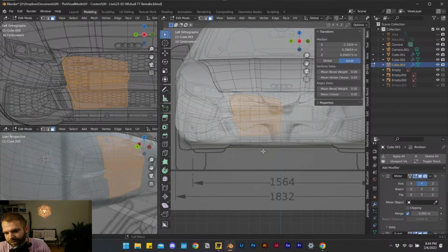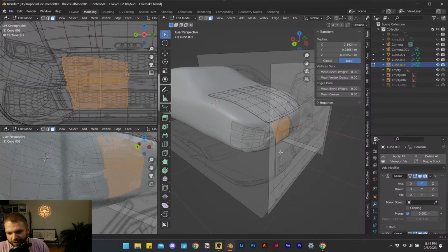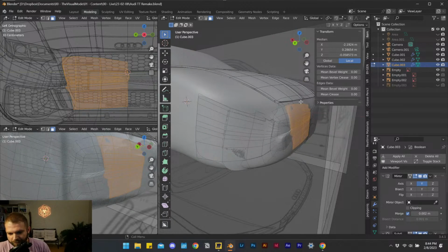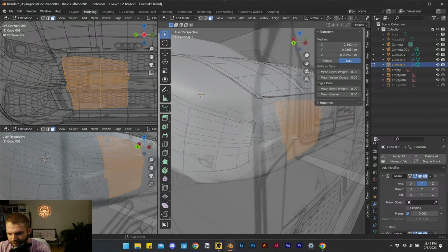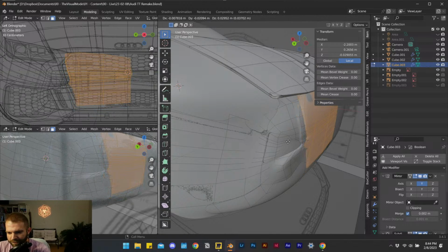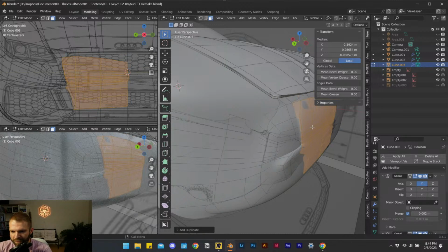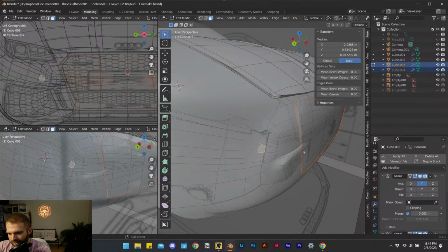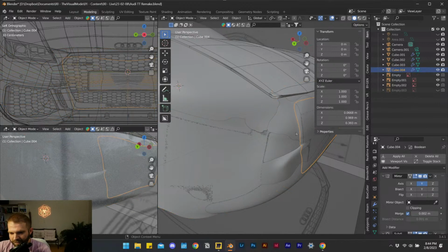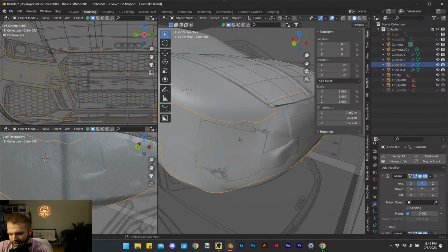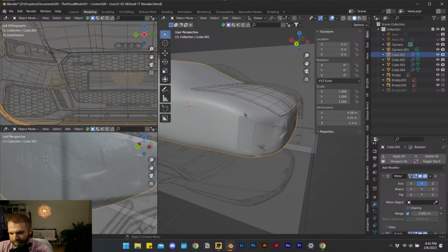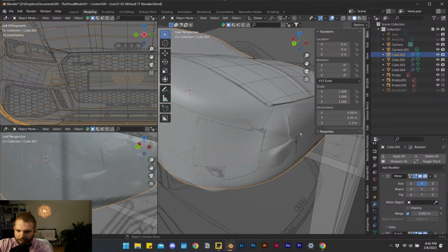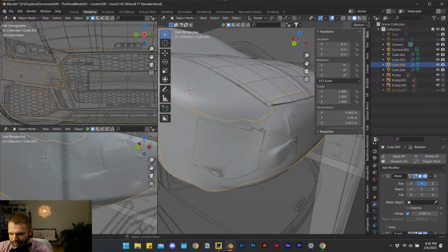So we're kind of entering different levels of detail here, right? We started with the box that yielded us the main shape of the car. Then we got into these different fascias or different body pieces of the car. And now we're getting a bit more detailed and actually picking out these different panels or different surfaces to break out. So I think always breaking things out, scaling down, not being afraid to copy this over and start working at it separately, as I did before, separating this little set of faces from the main set of front faces from the main body of the car, means I can always call back on that previous geometry and just start building on top of it.